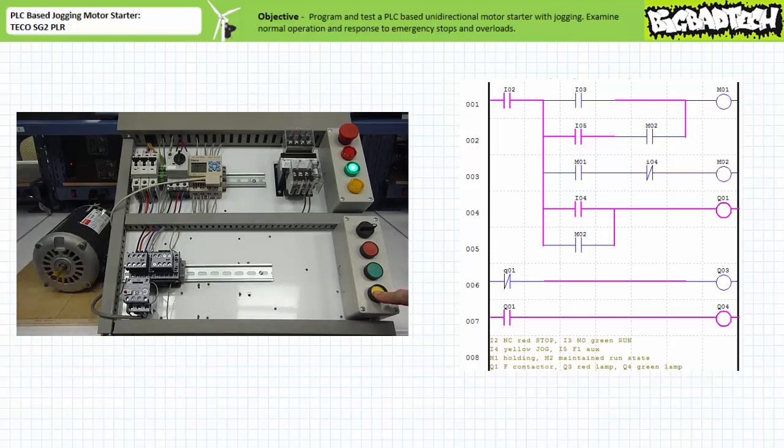As soon as an operator releases the yellow jog stop push button, the F contactor coil is de-energized, the F primary contacts open, and the motor turns off. The system behaves as anticipated for momentary jogging operation. A spring-applied electrical release friction brake could be installed in this system to increase the accuracy of the jogging movement.